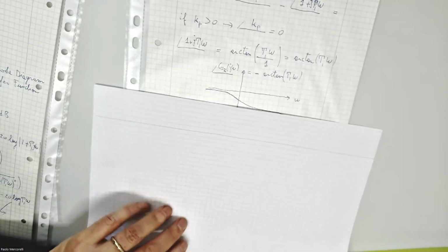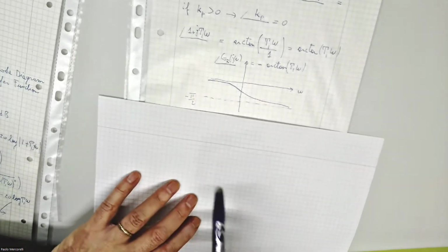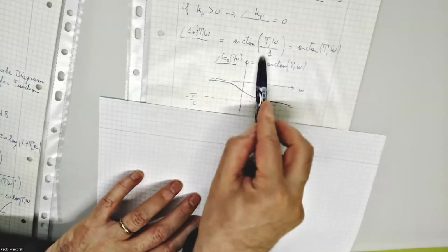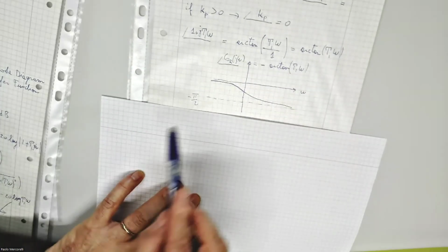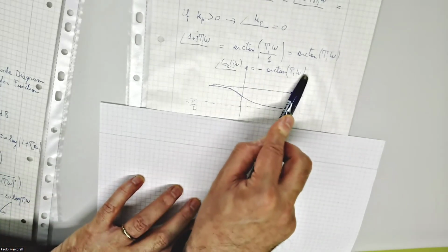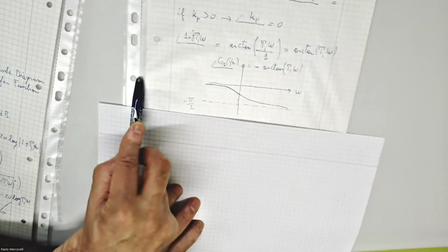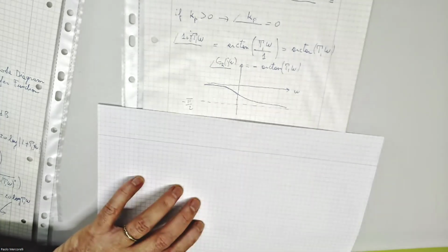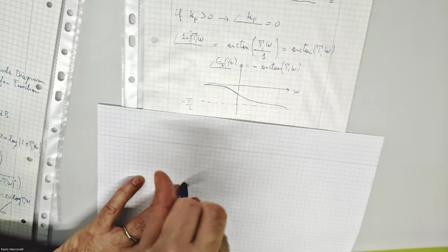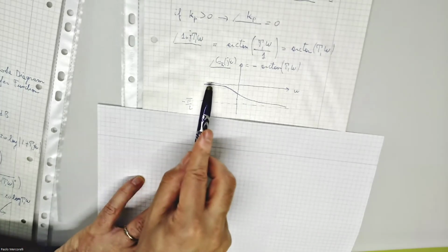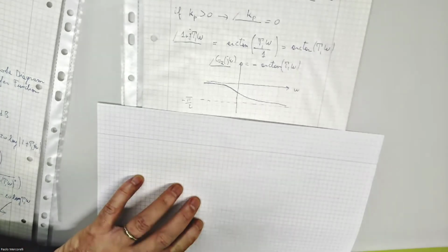Now, if I don't have the calculator, we can do the same analysis. The function is this one, the function is this one. But why do I directly graph in this form? The reason is that for omega towards 0, omega 0 is in this direction, infinitely far away, because in logarithmic scale, the logarithm of 0 is minus infinity.